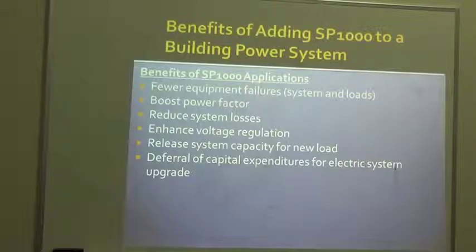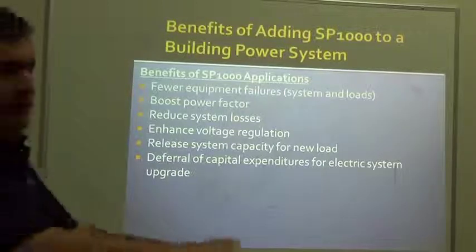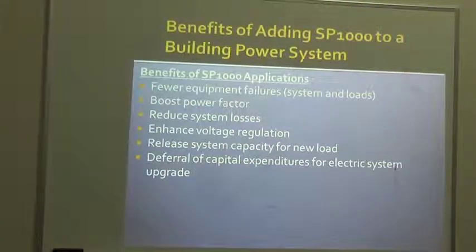Because these hospitals, number one thing about hospitals, the imaging departments can cause a lot of power quality problems, because that's where the large loads are. That and the HVAC support for the building. Hospitals, before data centers came about, were the buildings that had the most nonlinear loads per square foot of any other customer facility. The data centers blew them right out of the water, because they got stacks and stacks of servers. So hospitals have a lot of nonlinear loads. Think about how a hospital operates. You got fixed equipment, which doesn't move, large and small, and then you got lots of portable stuff. I'm pushing an x-ray machine from floor to floor. That's a pretty good size load, plugging it in here. So there's lots of dynamics in the hospital, and lots of risk involved, because in the ICU, you don't want the power to be bouncing around everywhere.